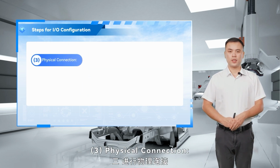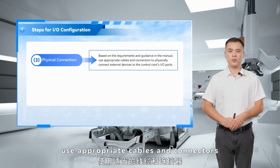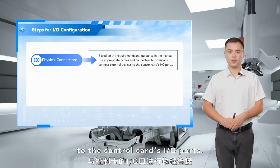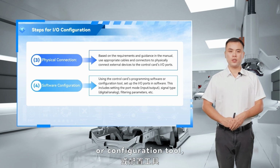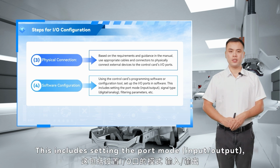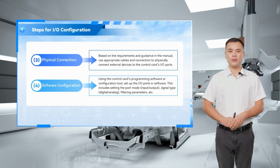3. Physical connection. Based on the requirements and guidance in the manual, use appropriate cables and connectors to physically connect external devices to the control card's I/O ports. 4. Software configuration. Using the control card's programming software or configuration tool, set up the I/O ports in software. This includes setting the port mode, input-output, signal type, digital/analog, filtering parameters, etc.